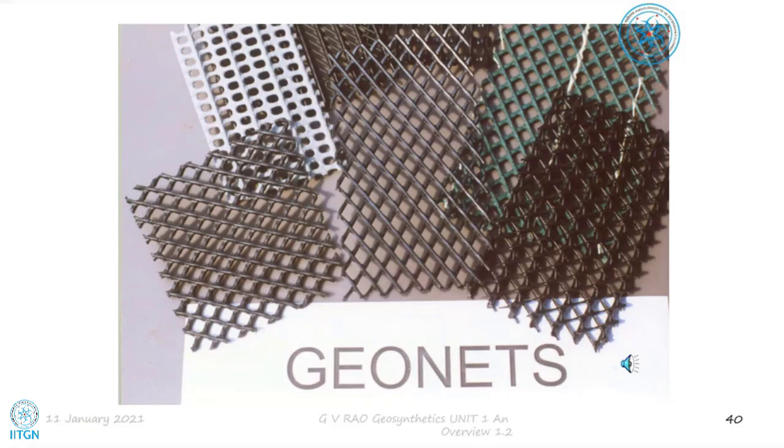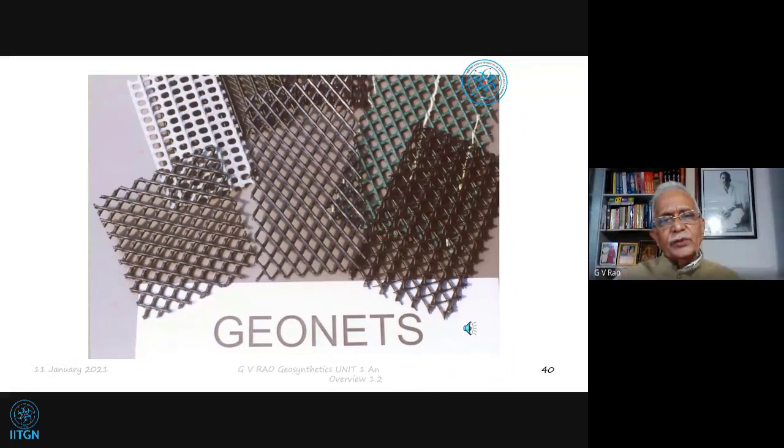So whatever movement comes out of the aggregates abutting the geotextile, I'm talking of a geotextile placed on a sub base, and then a base course is placed. That means stones are here, aggregate is here, also aggregate is here, and in between the geotextile is there. So if any load comes in which is going to pull out in one direction, let us say this direction, what is going to prevent it?